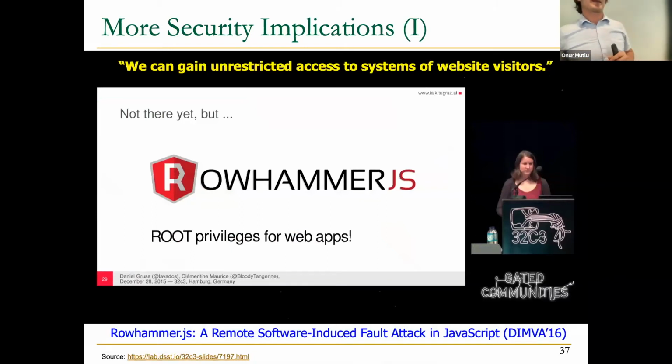Were they able to target specific bits, like using certain patterns, or was it just random until they got it? Well, they crafted a special attack because this is not easy to do. They sprayed the memory with page tables so that they increase the probability of the attack. So in the end, it's a probabilistic attack, yes. If you attack, for example, just the right enable bit in your page table entry that points to your own page table, that's 1 out of 64 bits. The probability is very low. But if you spray the memory with many page tables, now you change the pointer to a page table entry, and you actually increase the probability of the attack significantly.